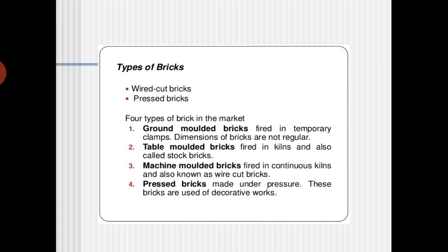Then, with the help of the wire, we cut it into the standard dimensions. Then we can call it wire cut bricks. But for pressed bricks, normally we apply pressure on the bricks so that they compact and take the standard dimensions.